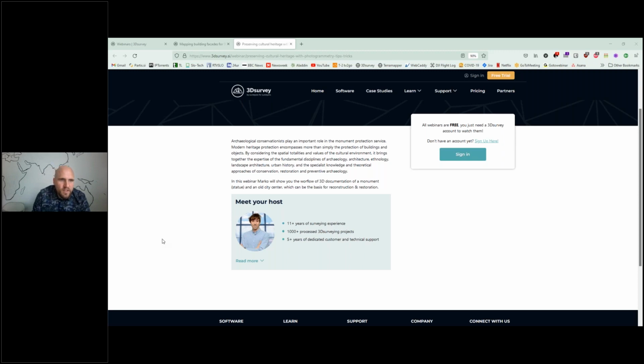Here I would say just record with your phone from as high as possible. So you will probably be recording at around 1 meter 80 centimeters distance or something like that, and you point the phone a little bit forward. With videogrammetry, it's quite hard to record from a higher distance, because then you wouldn't be able to see the picture. So you have to put the phone in front of you, and then I would recommend turning the phone down, for example 45 degrees forward, something like that, and then you're just moving around.